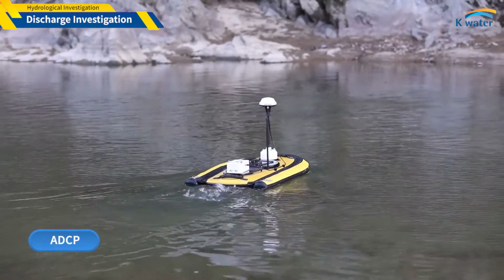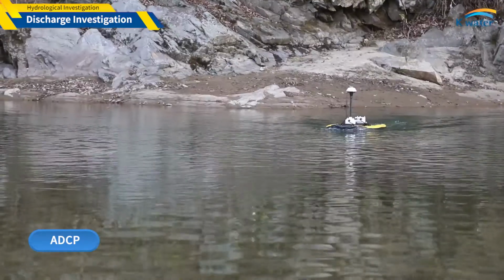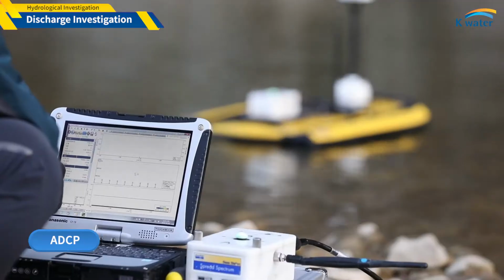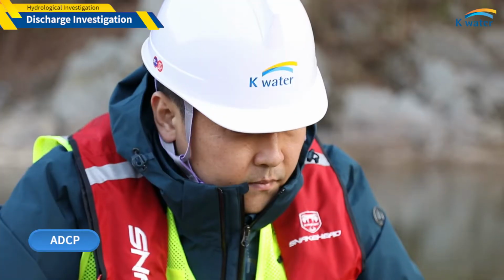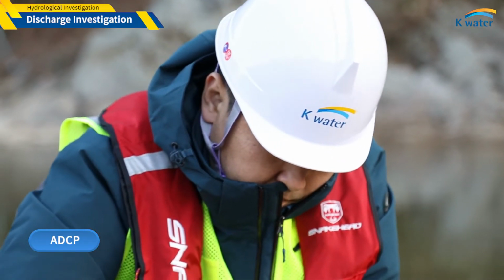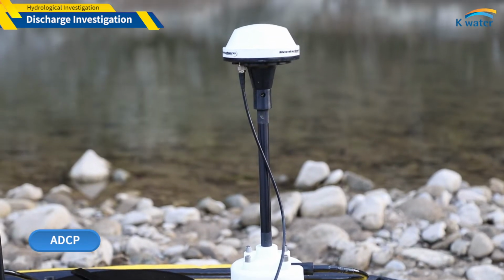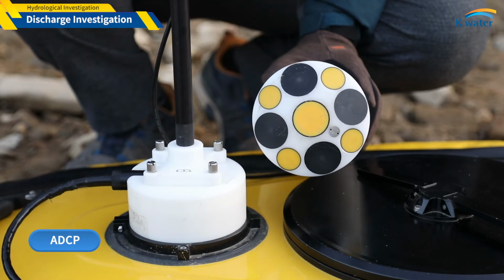ADCP, Acoustic Doppler Current Profiler, is used on a ship in a river with wide and deep water. Use a small uncrewed boat that can be controlled by wireless, and the operator must wear safety gear before measurement to prevent an accident. ADCP is a device that measures a three-dimensional velocity distribution using the Doppler effect of ultrasound.